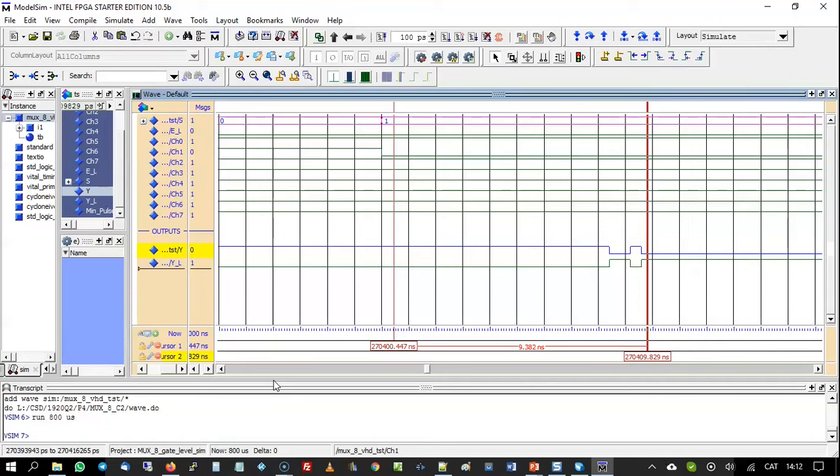All right, so from this 9.4 or 9.3, 9.5 measurement, you can measure the maximum speed of computing. To tell you something for this specific transition, if all the transitions will last that time, 9.5 nanoseconds, it's a frequency of 105 megahertz.